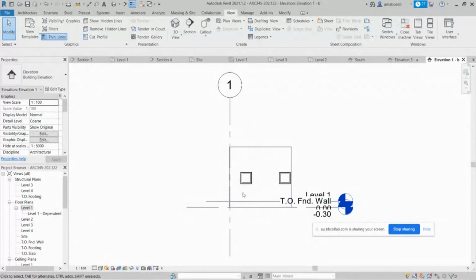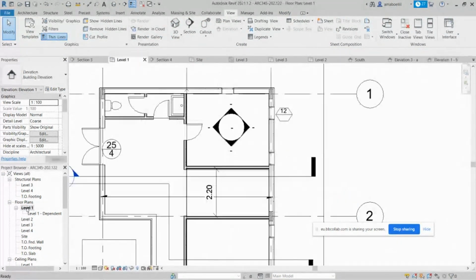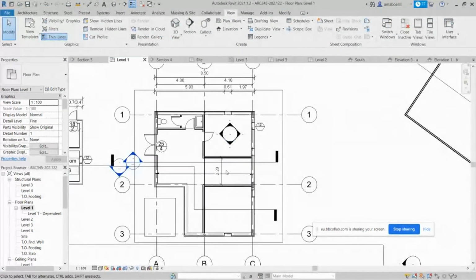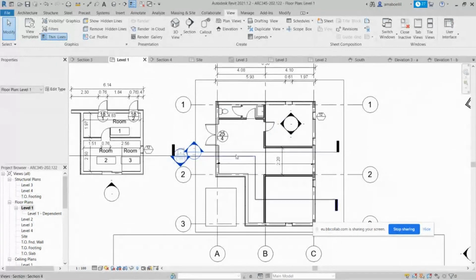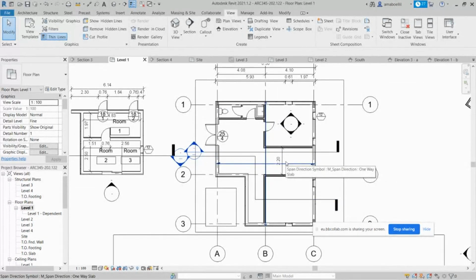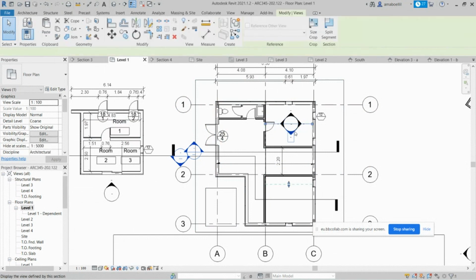Which is useful because if you want to go into more details in your interior space, you create lots of these in the spaces to reflect what the dimensions are, what the materials are. If you do have details in the interior, it might be useful also to show the 4 directions beside the room. But of course, once you place the room tag here, it's going to be crowded, so you can still adjust this, because this is a family. You can pick it, and then you can adjust the dimension of it in here and scale down if you want.